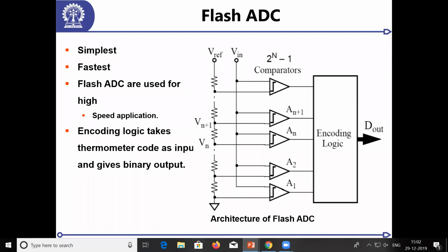Yes or no? Okay, so we got that. That means ln of V1 equals minus t1 by RC. Remember, I gave you one more capacitor. You plug in that capacitor over here. You know the value of this capacitor. So I apply the same voltage step and I get V2. So I can write ln V2 equals minus t1, the same t1, by R times C plus C1. Done. I've solved for C1. Similarly, I can solve for R. I can plug in R in the next measurement between the input and output.